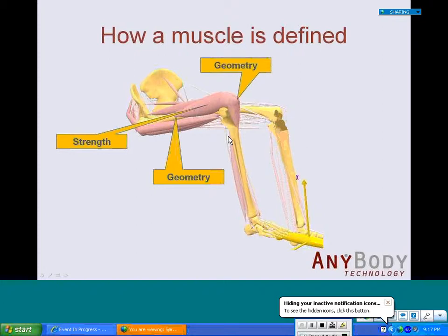And the way that these wrapping surfaces have been added to these models is that they have been defined through a number of nodes. So, for example, if we want to define a cylinder, we simply define a node defining one end of the cylinder, another node the other end, and a third node defining its radius. So these three nodes, no matter how they are moved around in space, will always be able to control the size and orientation of this cylinder. So this is how these wrapping surfaces have been implemented in a parametric way, controlled through nodes.